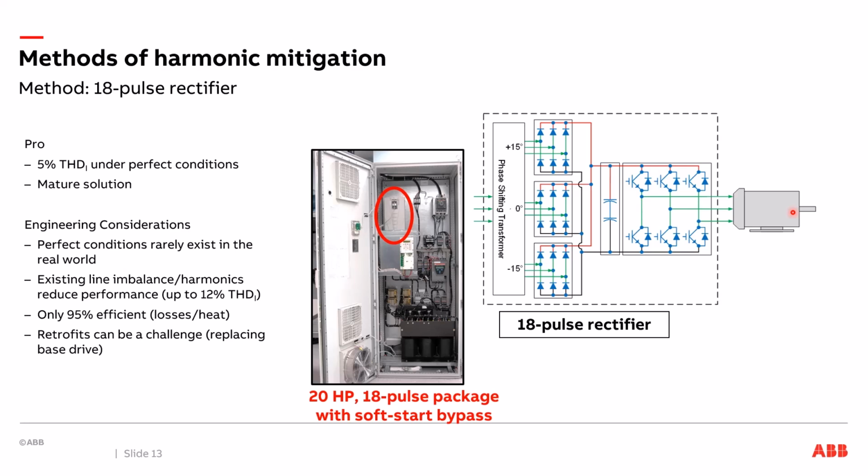And then the last part on it is doing retrofits can be a challenge. Depending on the manufacturer, there's different ways they do pre-charge circuits on the DC bus. So 10, 15 years from now, when the drive fails and they go to swap it out with the next generation drive, the pre-charge circuit may or may not be compatible with the new drive, or they might have had some custom boards in there. So I've seen some challenges with retrofits before where an 18 pulse drive just made it more challenging.